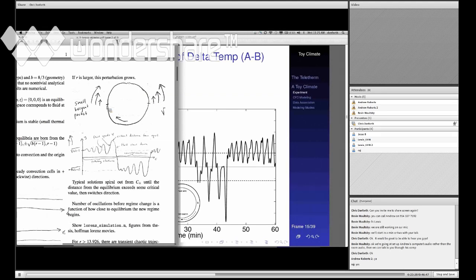So we have a little anomaly that has accelerated the flow and now decelerated the flow. It's still going in the clockwise direction, but it's sped up and slowed down. And now, since it's slowed down, this warm pocket spends more time heating as it comes through the bottom half of the loop. And again, when it gets over to point A, it's hotter than it should be and even hotter than it was last time. So it accelerates the fluid even more. That's a positive feedback. That's why this arrow is longer.